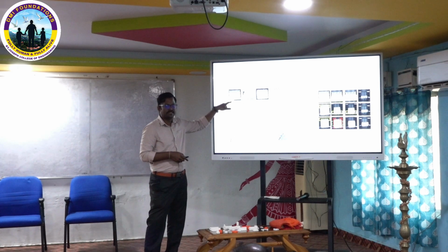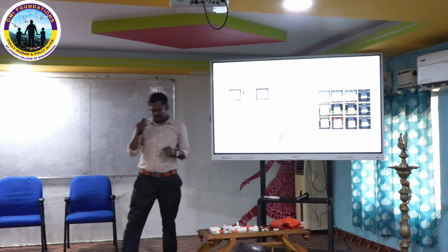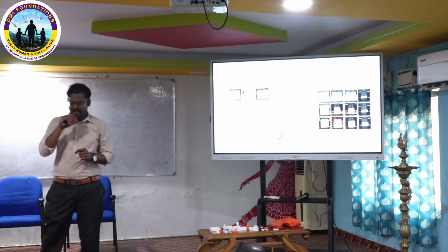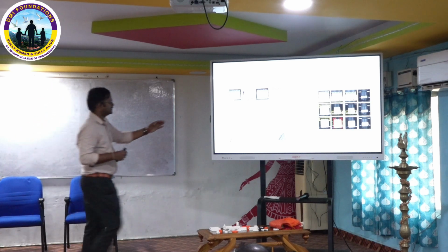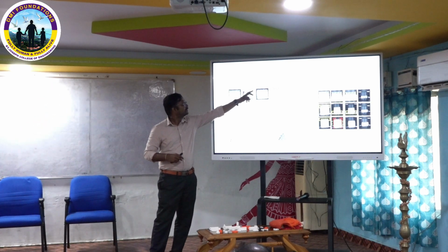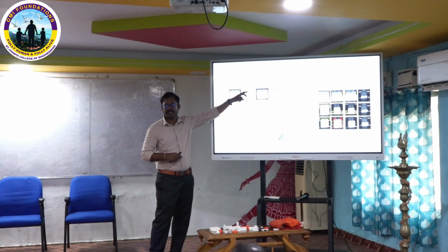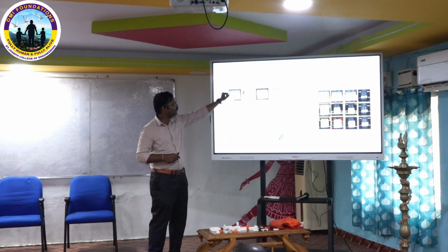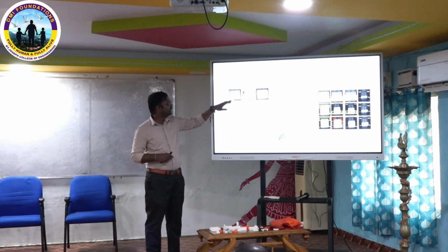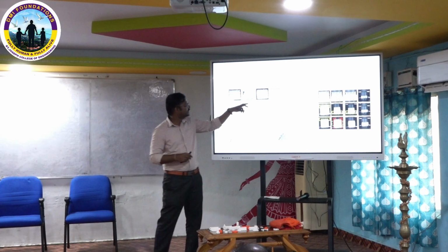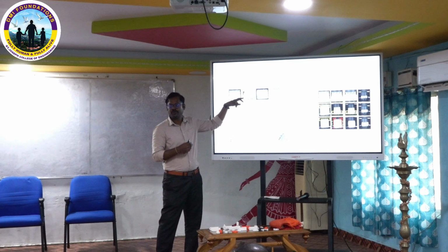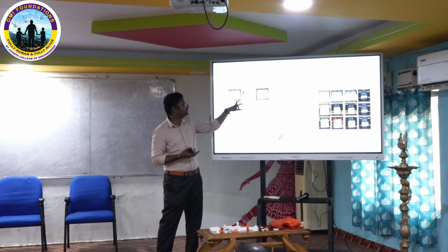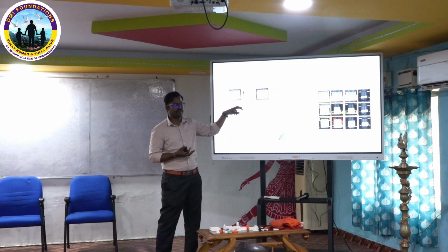First one is the struts. There is a stress pinpoint that happens. What happened now? When compressed, the struts get deformed, this kind of bending happens here, and after that only full compression happens. For the 10% and 20%, this pinch happens on the node area due to the higher dimension, higher relative density. So this kind of two things we observed.